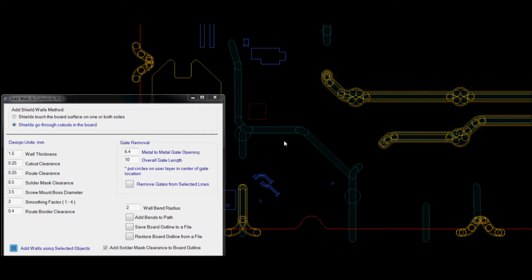The lines and circles can be of any thickness and size, as the software will use all of the provided parameters to draw the actual features. It is also important to note that the software contains an algorithm which combines all the shapes into a single continuous shape for each cutout, with a radius added anywhere there is a sharp corner junction. The size of this radius is controlled by the smoothing factor value.